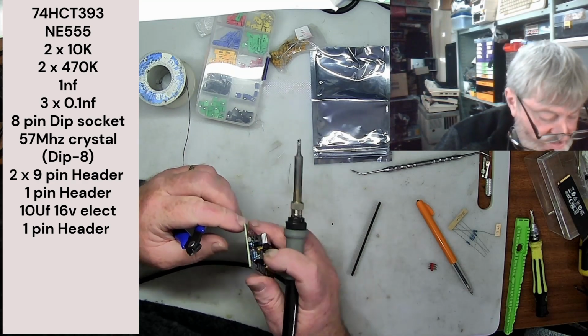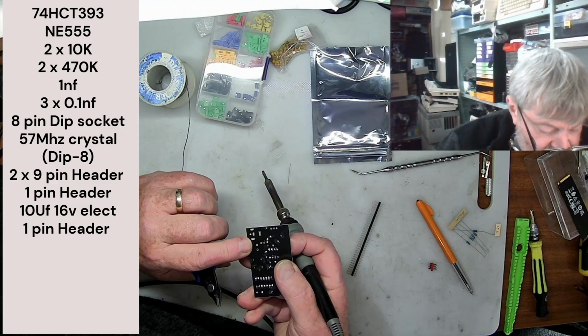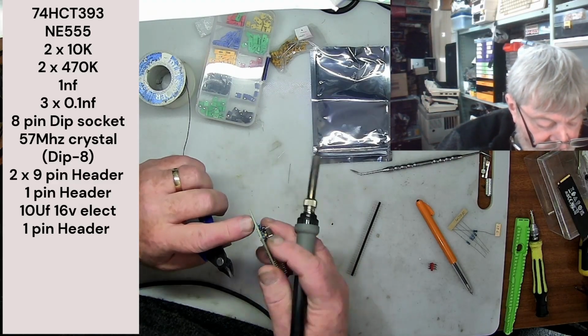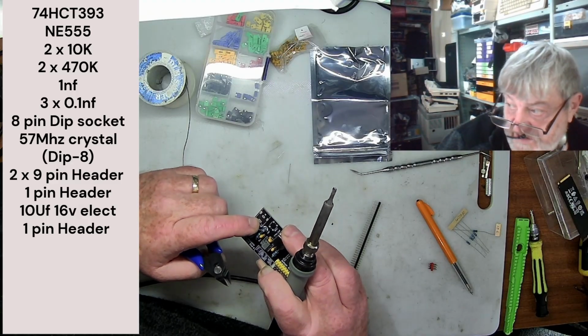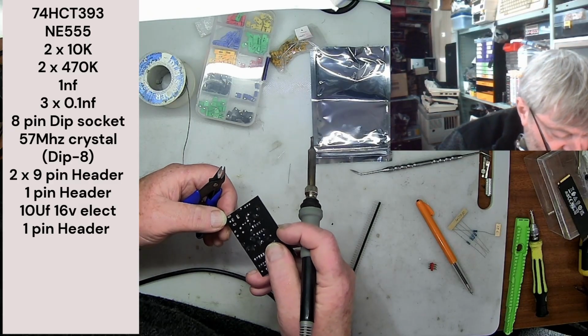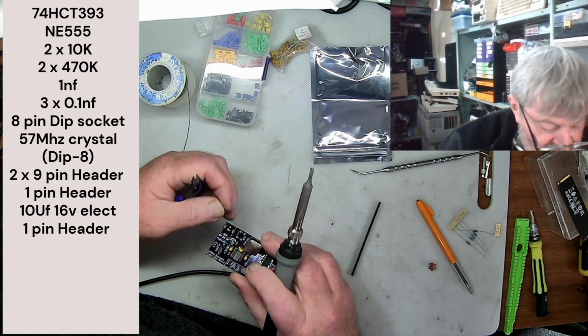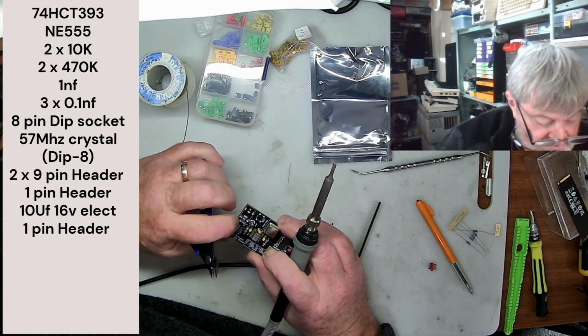And as I said, a ground, once I put something in here, I can pull ground off of this. My ground plane is the bottom plane, my power plane is the top plane here. So this back pin is my plus, the middle pin is my ground, and the same as, I haven't done it, but these outer ones should be set to ground as well. But they're just mounting, they're for stress relief, so those are my two main ones.